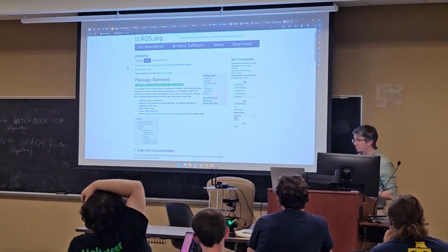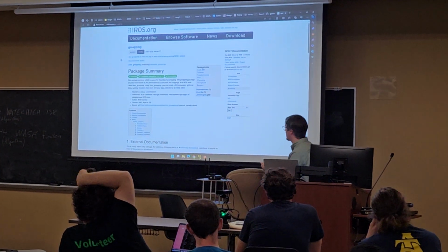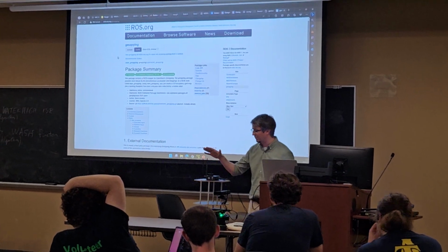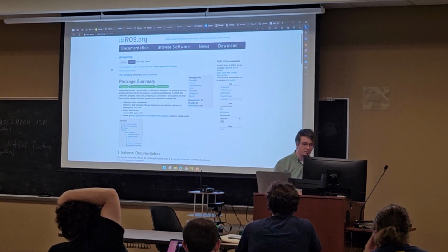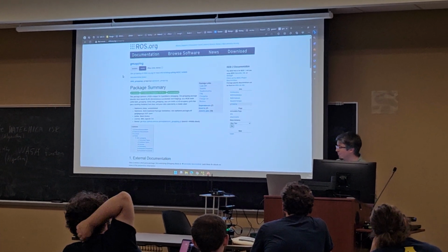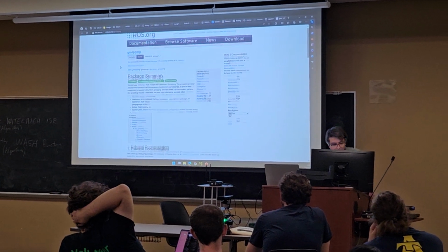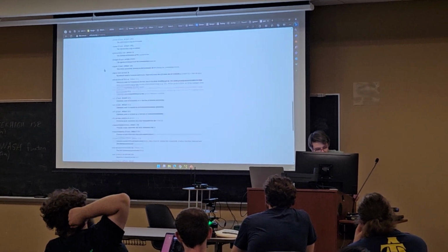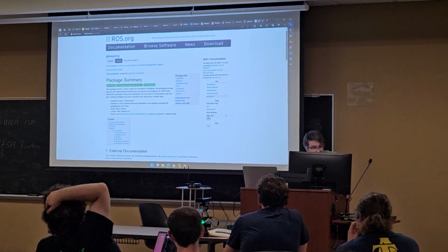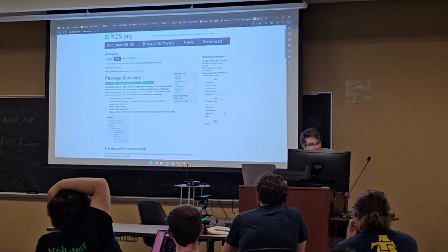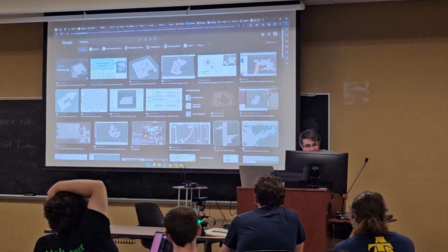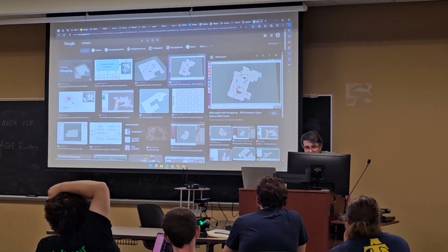So if I wanted to build an autonomous mobile robotics application, one of the first things that I need is a map. And we can build maps with ROS using something called GMapping, which is a type of SLAM algorithm where it's simultaneously localizing and mapping in its environment. So what GMapping will do is, I didn't include a picture here. Somewhere there's a picture. Yeah, Google's gonna find me, there we go. That's a picture from RViz. Perfect.